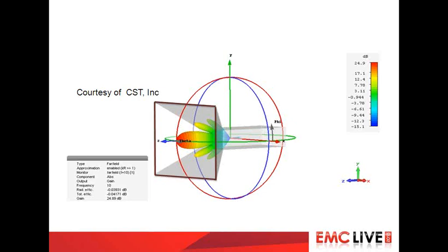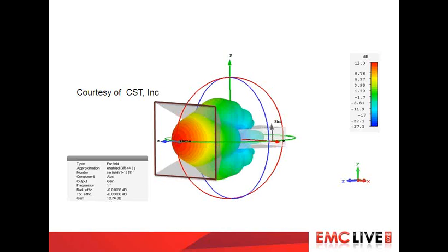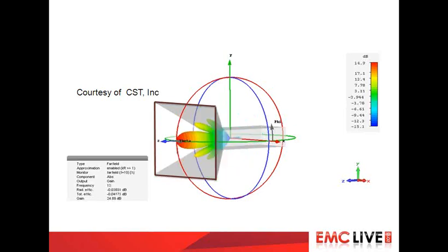Now, this is a webinar, so I'm not sure how soon your screens refresh. But I'm going to go back up to the original 1 gigahertz data, count to 4 seconds, and come down again, and hopefully it won't look too messy on your end. So going back to the first one, look how big the lobe is. There it goes. I'll give it 1, 2, 3, 4. Hopefully yours is there. I'm now going back. 1, 2, 3, 4. Hopefully you saw the trade-off there with this very poor antenna, where you've got a tremendous gain improvement, however, at the cost of beam width.